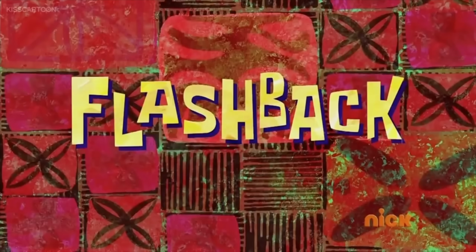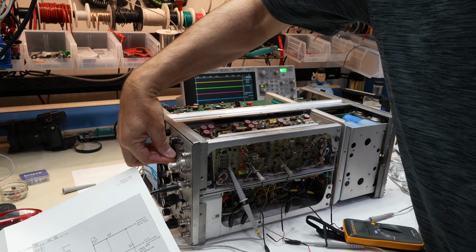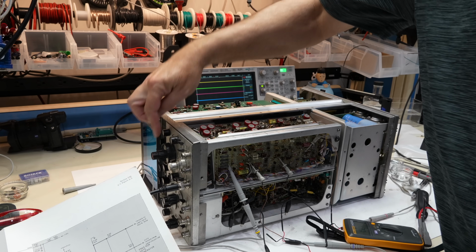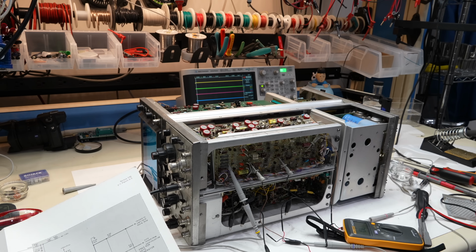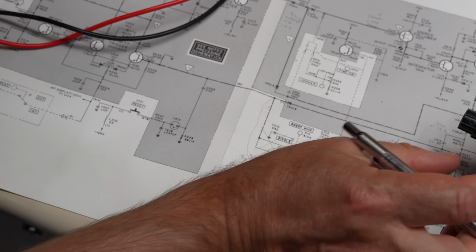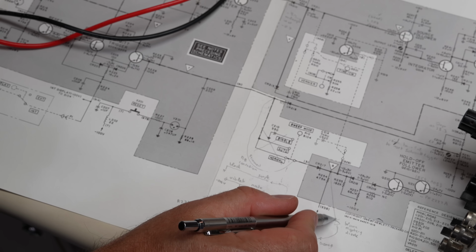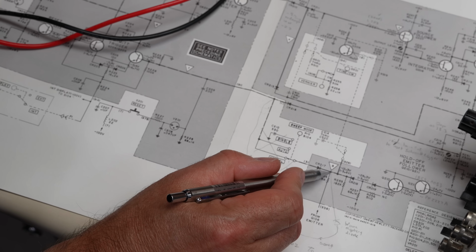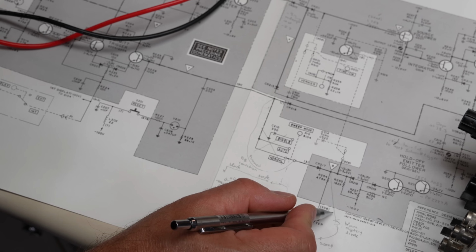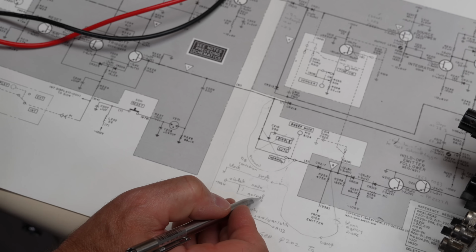Smokes the diode. Flashback. I was trying to figure out if I could get it to reset in single sweep mode. I heard a distinct small pop towards the back of the instrument. End of flashback. Then I switch it back to auto, and now that diode is a short, and my 12.6 short here has a second short here that shorts to minus 100 volts and disables my power supply.